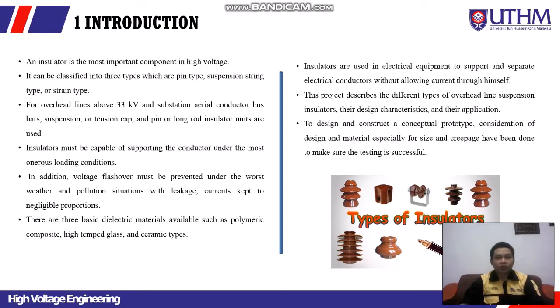For overhead lines above 33 kV and substation aerial conductor bus bars, suspension or tension cap, and pin or long rod insulator units are used. It must be capable of supporting the conductor under the most onerous loading condition.